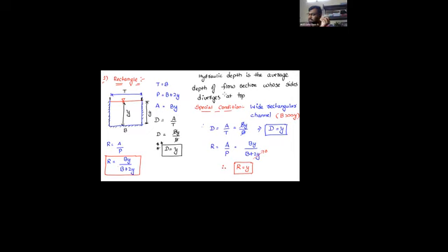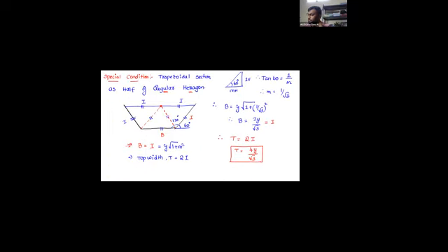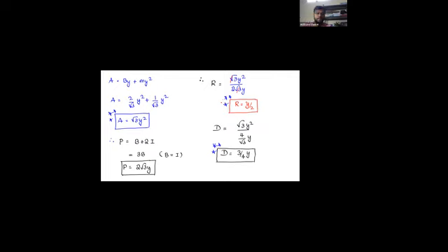In the case of the circular section, for the people who have attended environmental engineering, I'm going to say the basics again. In environmental engineering, part 2, wastewater engineering, chapter 2, design of sewers, you design the sewer by assuming the flow as open channel flow. I hope you remember that. And while designing, you use Manning's equation, right? By using Manning's equation, there are some formulas for the circular section.